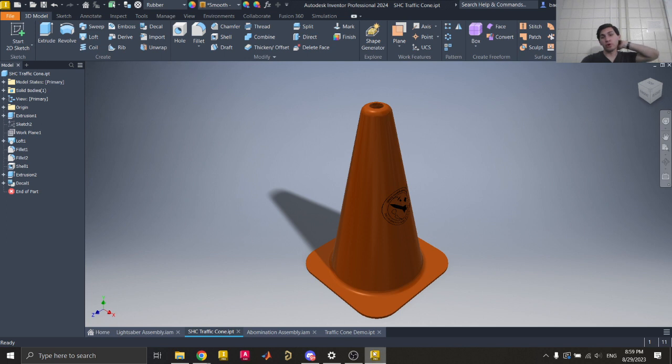And they're all in some sort of an order, and the order of these does matter depending on how you want to make the thing. Think of anybody who has worked in a Microsoft Word document, some big long report. You have a picture somewhere, you change the size of that picture from 4 inches to 5 inches, then it throws off the next 30 pages of your work. It messes up all the formatting. In CAD, you can do the same thing if you don't do things right. Whatever you do up here will affect everything that happens down below it, but it won't affect all the things up above it. Just like a Word document, basically.